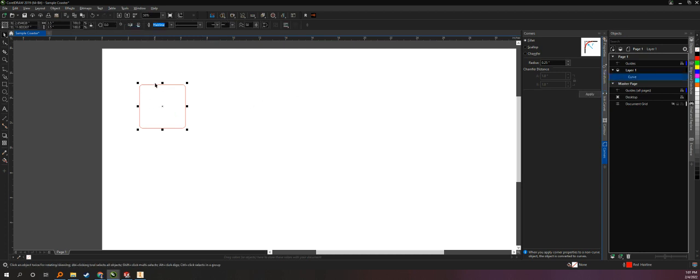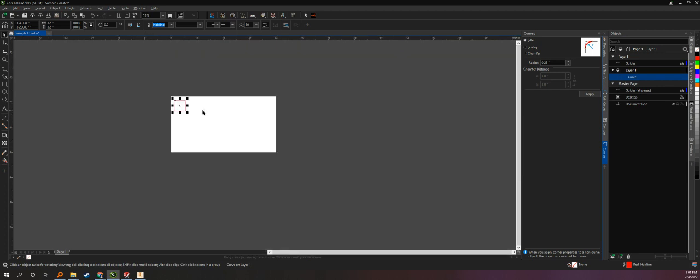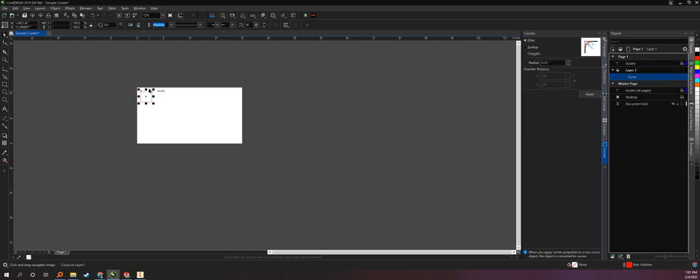Now when we position items to prep the document for use in the laser, we offset it 1/4 inch from the border to make sure we have enough room from the edge of the material to not overlap when we cut it. It's always going to be a 1/4 inch offset from the edge. So the universal laser, we offset, the 0 point is in the top left corner, and the Kern, the 0 point is in the bottom left corner.